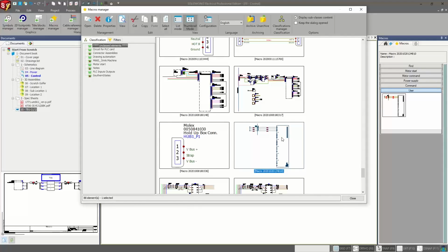So if I am in charge of the input power circuit with the input connector and the EMI filter and the ground stud, and if I want to show it, and all the ring terminals and everything associated to it, and the actual power supply and the Molex connectors associated, whatever it is, I can build a macro, put it in there, and as soon as I create that, it is now available for somebody else to reuse in another project right then and there with all of that information in there. So I don't have to go and ask, hey, what was that project that you built that entire circuit? I need to copy it out and bring it into this one and whatever else. It's there. It's ready for you to use right away.